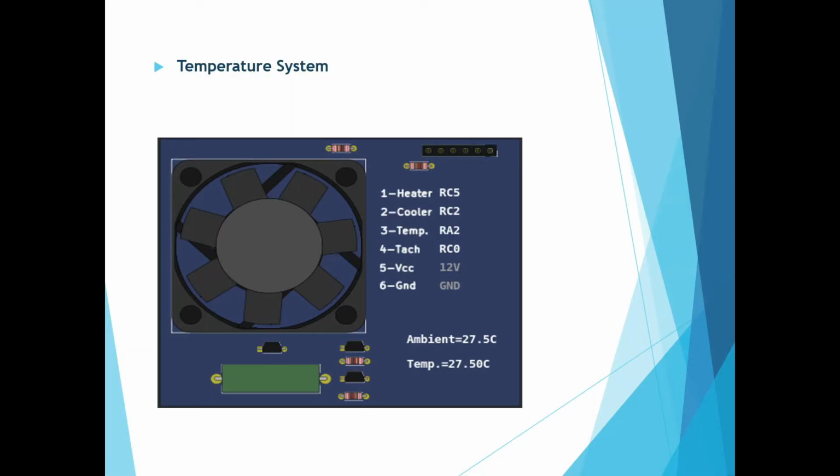The LM35 device doesn't require any external calibration or trimming to provide typical accuracies of plus or minus 1/4 degree centigrade at room temperature and plus or minus 3/4 degree over a full minus 55 degrees centigrade to 150 degrees centigrade temperature range. Its technical specifications are: calibrated directly in Celsius, 0.5 degrees centigrade ensured accuracy, suitable for remote applications.